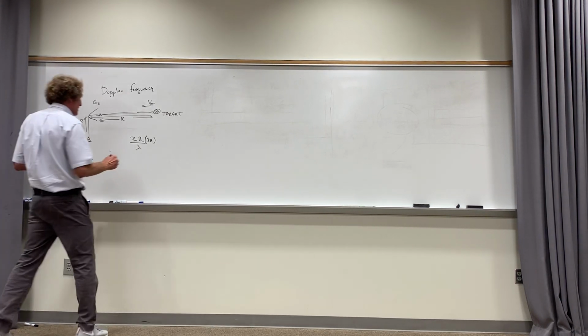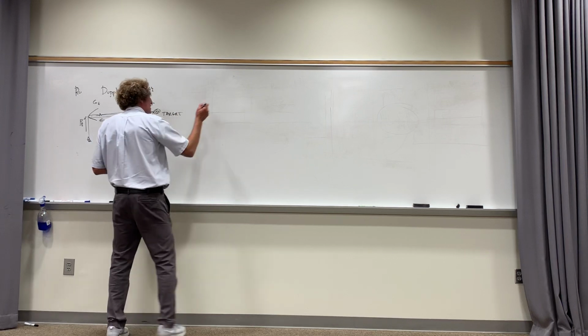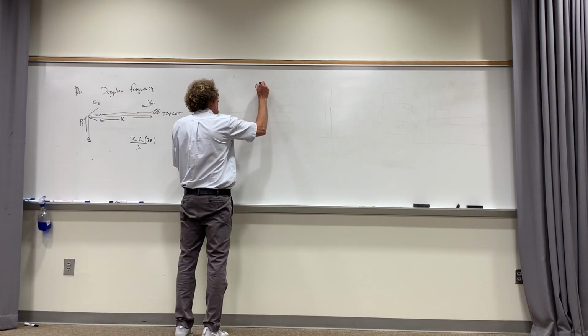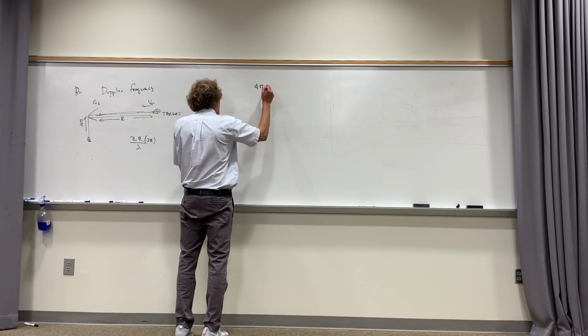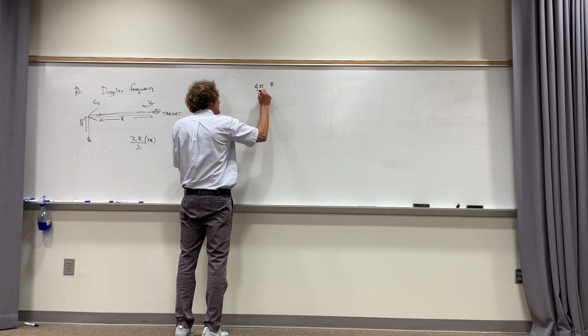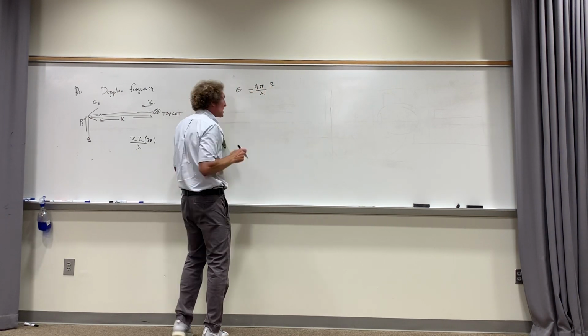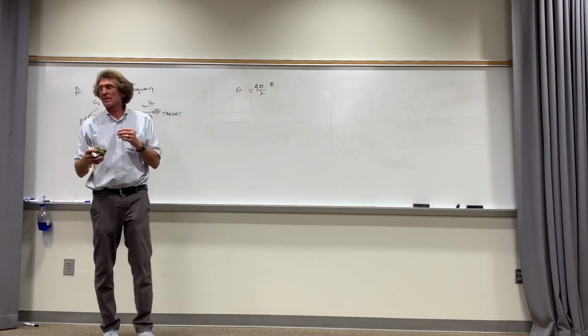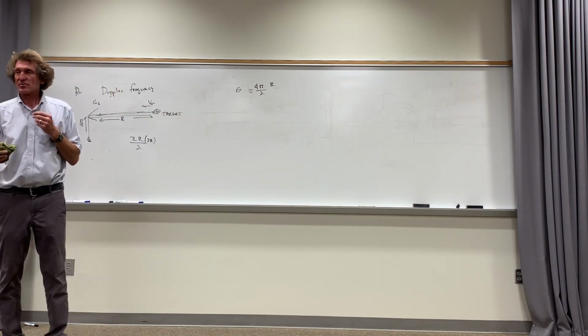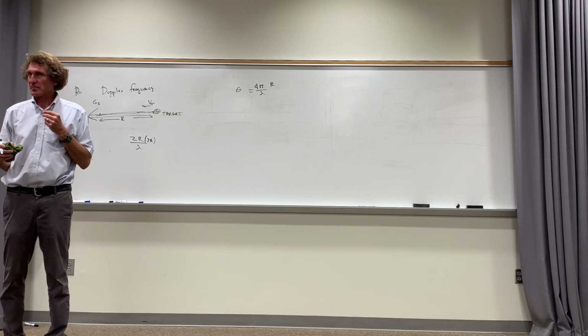And then I can say, let me write that over here. That's really 4 pi r over lambda. And that's the actual phase of the wave. Think about that, the amount of phase that the actual wave underwent, or phase change.